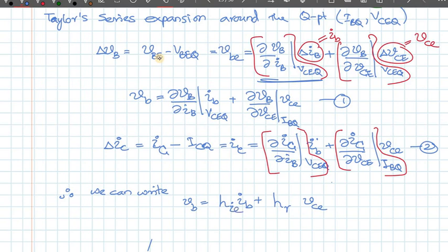So therefore, because it is a common emitter expression, I'm going to write the second subscript as this, because these are the same equations, right? So if you compare 1 and 3, this comes from small signal active linear two-port theory. So therefore what you have inside this expression has to be my HIE, and whatever is there has to be my HRE.